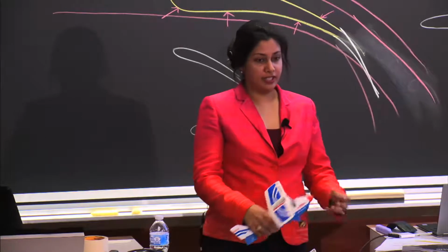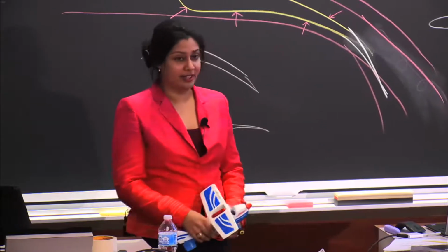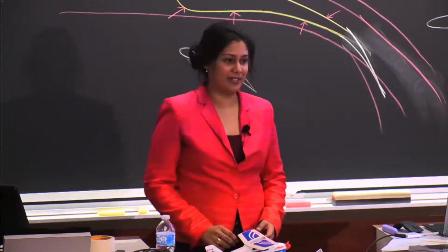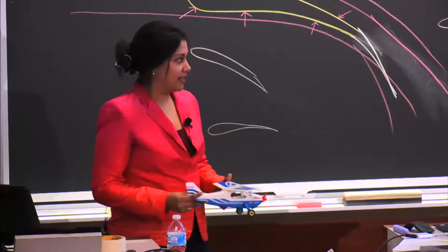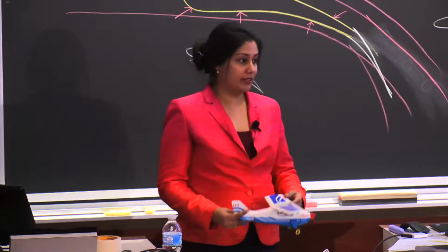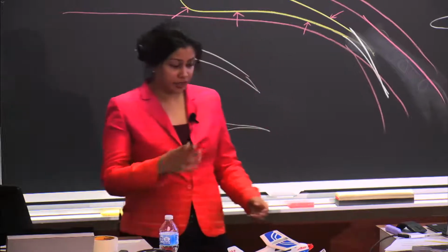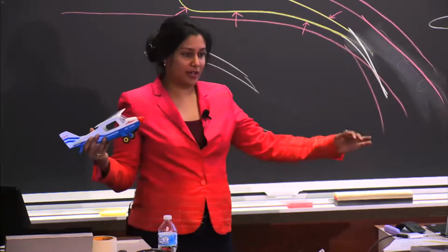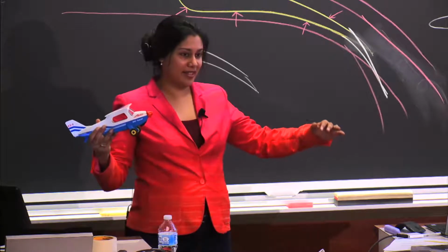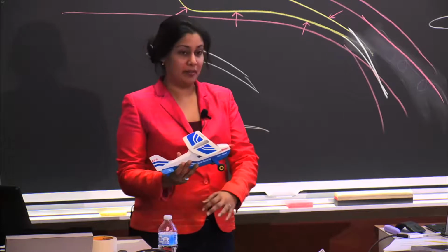Yeah, the reason that you, especially on landing, many times people use flaps on takeoff as well, but the reason is just that you like to have your aircraft configured that in case you didn't take off, you can land without making a lot of dramatic changes. The reason that you do that is basically that by increasing your lift, but also increasing the drag, drag affects how fast you're moving forward, right? And so you can actually have your airspeed be higher with the ground speed being lower.